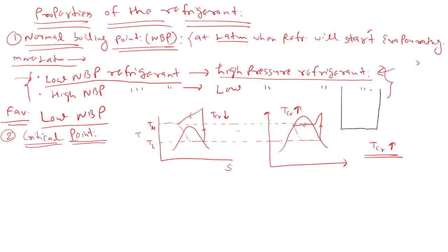If vapor goes to the expansion valve, the temperature will try to reduce, and so many disadvantages would be there. So I will start writing here: if it is vapor here, then its enthalpy would be high, right? First is this. Is it clear? Yes sir. Its enthalpy would be high, and then the same enthalpy would be here. Then if enthalpy is very high, what would happen to the refrigeration effect? It would be less. Is it clear?